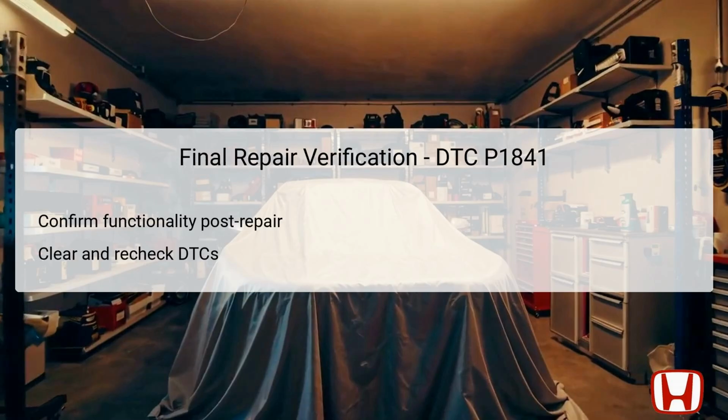The final repair verification step involves confirming the functionality of the vehicle post-repair. After implementing necessary repairs or component replacements related to the DTC P1841, it's essential to clear any stored DTCs using the HDS. After clearing, recheck the DTCs to ensure that the error code does not reappear.